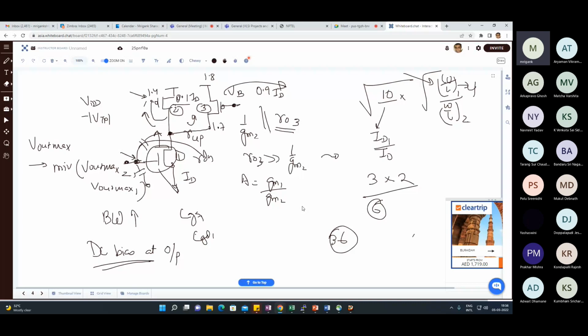So once you know that, okay, how do you calculate the bandwidth of a circuit, looking at the nodes, figuring out what is the impedance over there, what is the small signal capacitance over there, you can figure out what is happening to the speed of the circuit, which node is going to contribute to the bandwidth limitation, which node is critical for the Bode plot. Those things you can analyze.